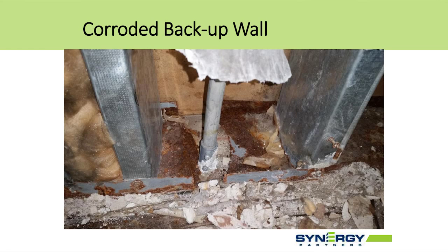In this case, this is a steel stud backup. So the other wall we were talking about had a concrete block backup. A lot of buildings built starting in the 80s were built with steel stud backup and drywall interface, and then an airspace, and then the brick veneer.